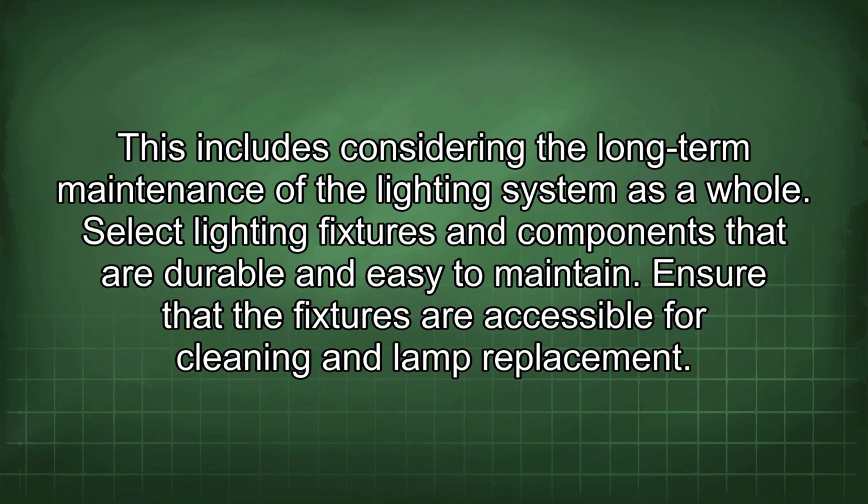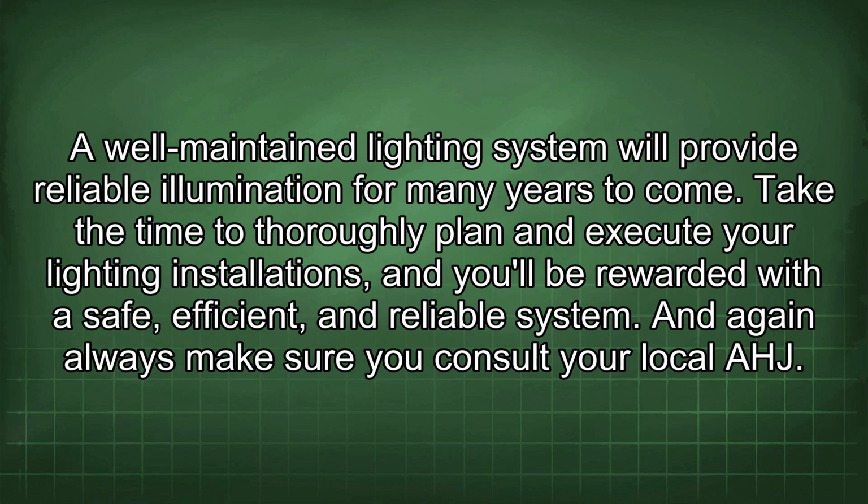This includes considering the long-term maintenance of the lighting system as a whole. Select lighting fixtures and components that are durable and easy to maintain. Ensure that the fixtures are accessible for cleaning and lamp replacement. A well-maintained lighting system will provide reliable illumination for many years to come.